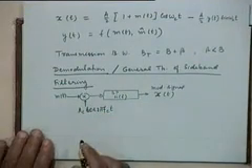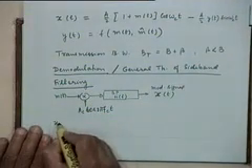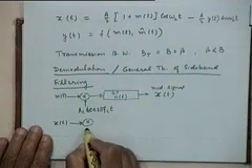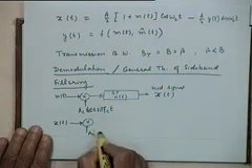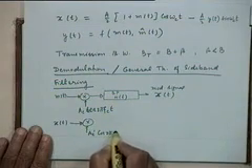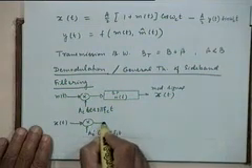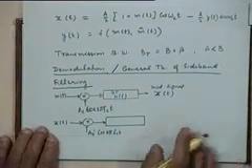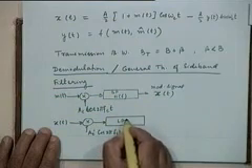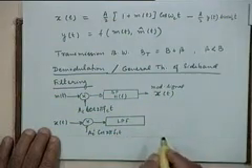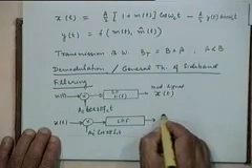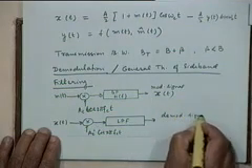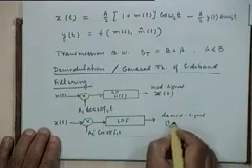And you get this x(t) here. The demodulator multiplies it with A_c prime cosine 2 pi f_c t, and for demodulation what do you normally do? Put a low pass filter here. That is your synchronous demodulation, and you will get a demodulated signal, let us call it v_o(t).